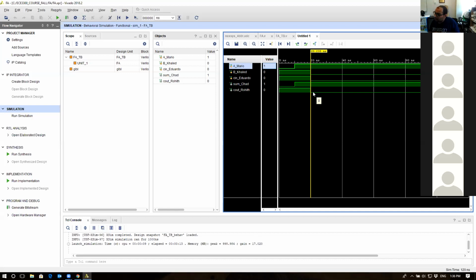If you remember the ripple carry adder, the carry out of the first bit will be the carry in for the second bit, and the carry out of the second bit will be the carry in for the third bit, and so on. So it's like threading. So the wave propagation delay will be significantly increased. Do you remember when I made the 1 bit full adder delay in front of you?